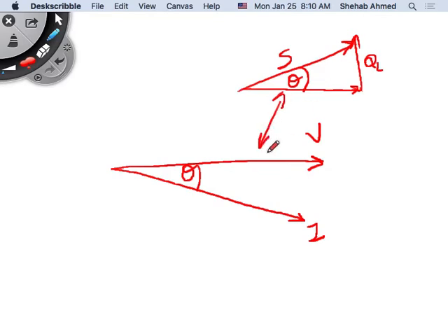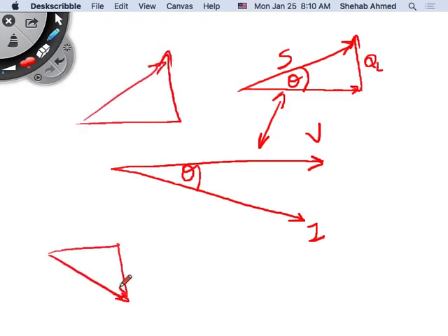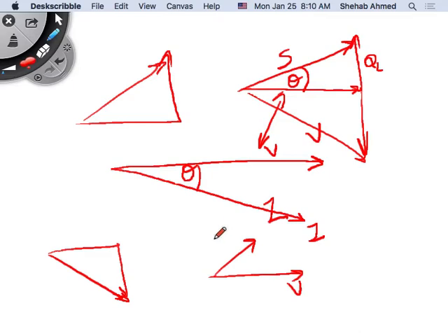Okay, so I think it's because the standard is that we have inductive reactive power in the system, right? So when we wanted to draw the power triangle, I guess they wanted to represent it in this fashion instead of drawing a power triangle down here. Honestly, I don't know why they use the conjugate, but what it does is confuse you a little bit when you draw this lagging power factor versus the power triangle. So this means lagging, and this means leading power factor, versus when you draw the voltage and current, this is lagging, and this is leading.